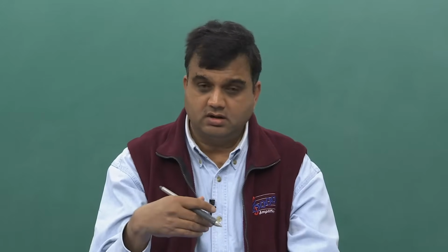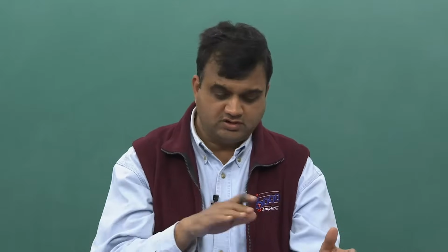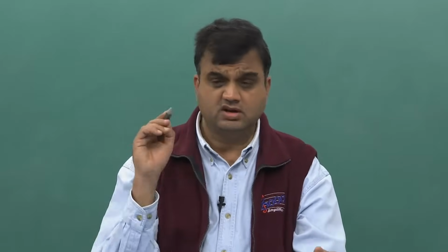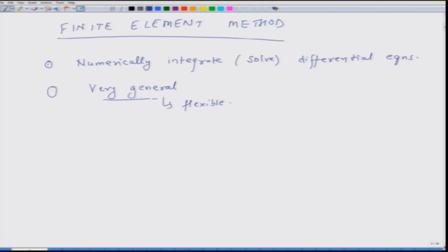But when we start using techniques like the finite element method, this method is more or less insensitive to the type or form of the partial differential equation, because the philosophy on which it rests, and you will see it as we walk through in detail, is very generic. So, it does not matter whether the equation is of this type or some other type, whether it is homogeneous or non-homogeneous. If we understand the overall theory of the finite element method reasonably well, then we should be able to solve or integrate these equations which capture the essence of several physical processes with a fair amount of accuracy and reasonableness.